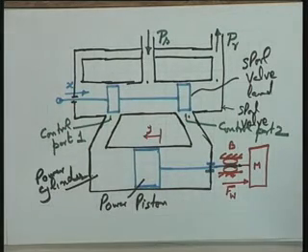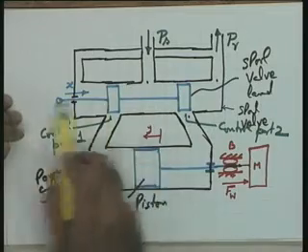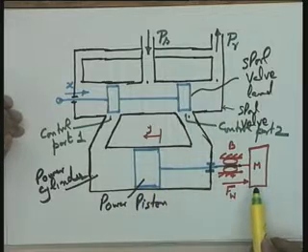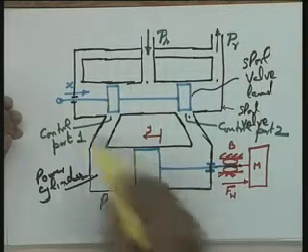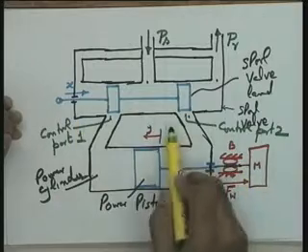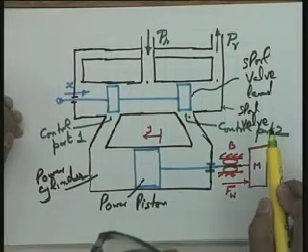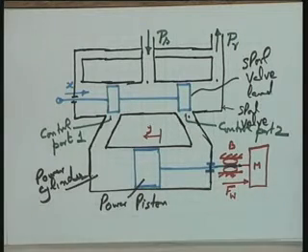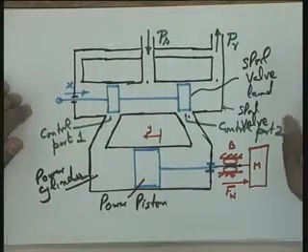The objective you have to keep in mind is that for a small displacement X, you get an appropriate displacement Y, which moves the load. And the dynamics of the system naturally will come into the picture. Y and X will not be related by a static relationship. Whether it's first order dynamics, second order dynamics, or higher order dynamics, that also we have to see. So this is the total picture of the device called a hydraulic linear actuator.